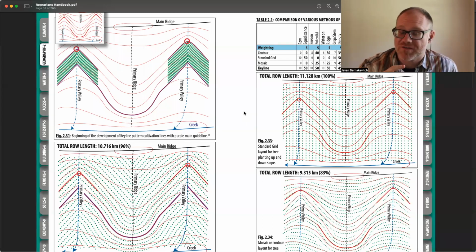And it was mostly due to the fact that the trees that were planted along the keyline pattern of cultivation had roots acting as a pipe drain. So water was traveling along these roots. But that water was traveling maybe an inch or 2 inches. It wasn't traveling that far, but over time you have all of this little water precipitation that's moving this way, and the ridge was actually getting wet. And this is the great genius of Keyline as created by P.A. Yeomans, that through time, effort, and biological process, it moves moisture towards that ridge.